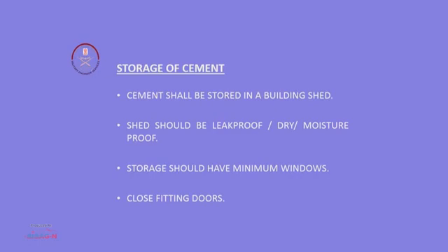Within no time it will set, or it will lose its original property. That's why storage of cement is very, very important. When cement comes on the site, first it should not be stored in the open. It should be stored in a building or a shed specially made for the storage of cement, and that shed